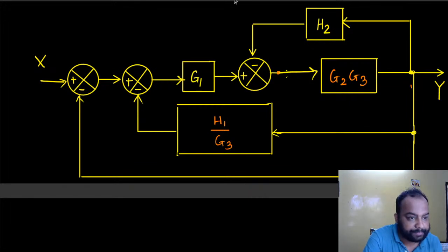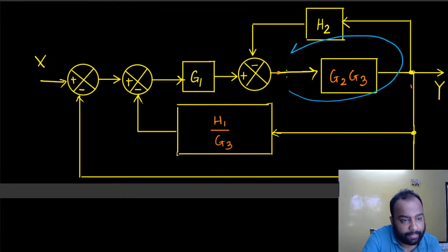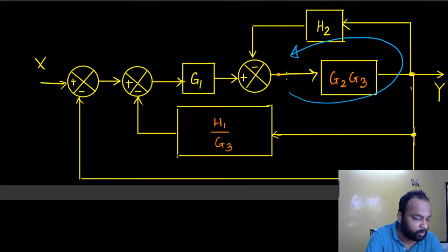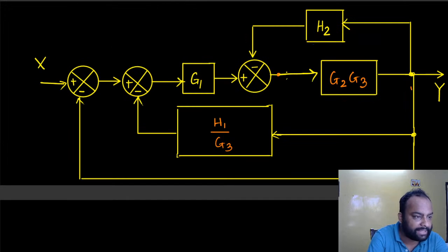Now this is my feedback loop, right? So let's construct the feedback loop. In the feedback loop, this is the feed forward transfer function, like your G, and this is H. If I combine this entire feedback loop into a single one, let's copy and paste once more.